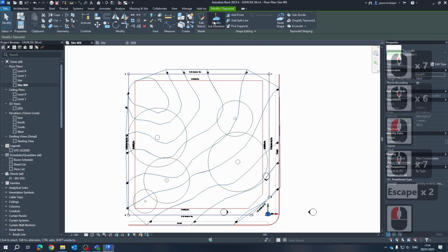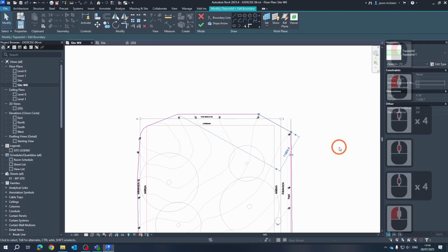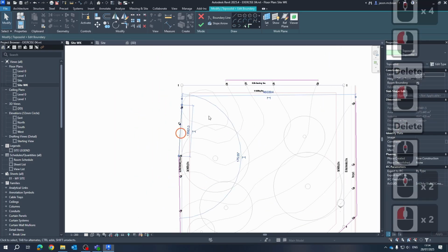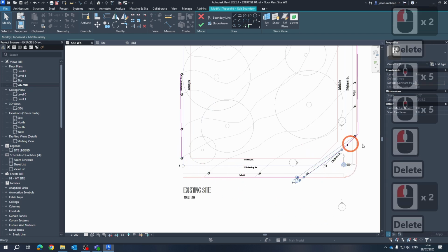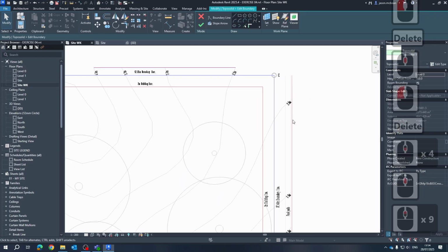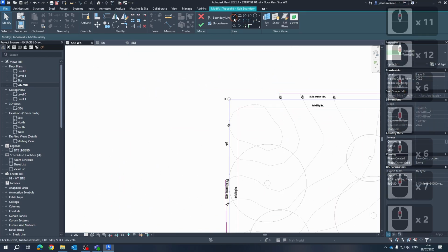Okay, first things first, I'm just going to fix the boundary. So I'm going to go and edit sketch, and I'm going to get rid of these diagonals for now. So I'm going to get rid of that diagonal, get rid of that diagonal, get rid of that. That's fine, it gives me a straight line, get rid of that. And I'm just going to keep one straight line on the edge here. Okay, so we could just make this a square, for example. So I'm going to create one straight line.